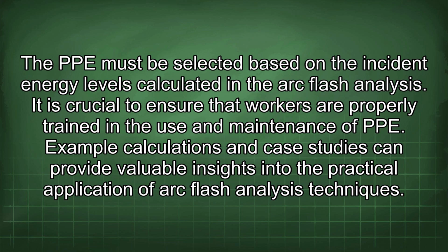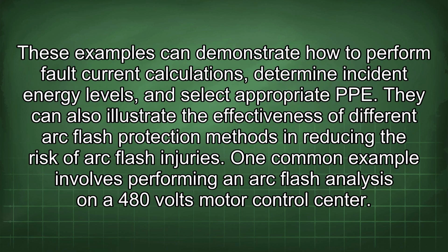Example calculations and case studies can provide valuable insights into the practical application of arc flash analysis techniques. These examples can demonstrate how to perform fault current calculations, determine incident energy levels, and select appropriate PPE. They can also illustrate the effectiveness of different arc flash protection methods in reducing the risk of arc flash injuries.